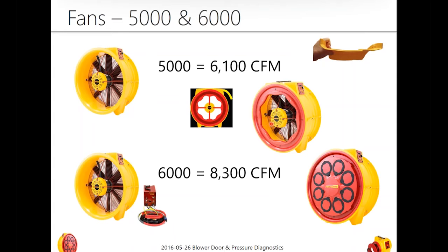You'll notice that it also has a pretty obvious shape. That also helps so that this fan cover, which is held on with a super magnet, you'll see the magnets here, makes it easy to pull off and put back on. You'll also notice that now the range plugs have changed significantly. These are the exact same range plugs that are used for the up-to-date 300 fan, which is a duct tester. So those are interchangeable. If you're testing something very, very tight, you can plug up all these and use one of the smaller duct tester range plugs to plug up the hole.